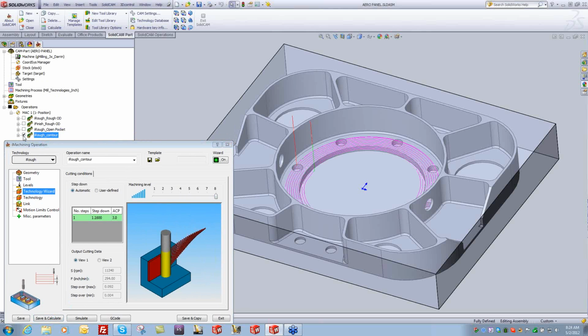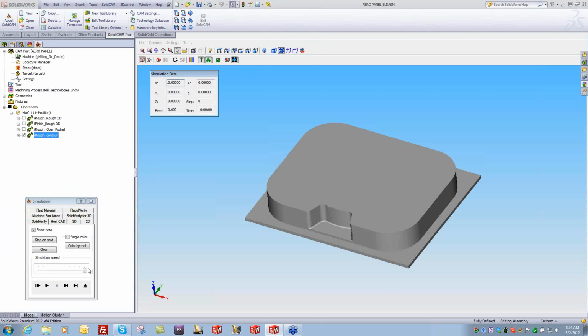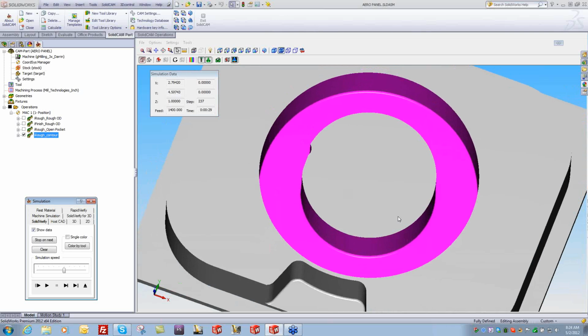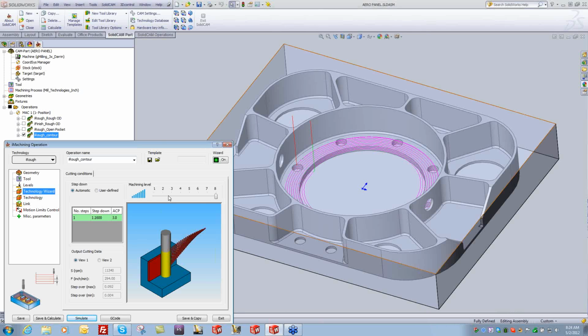And if I did that right, we should get a good tool path, which we did. And we'll turn that down a little bit and let it run. Now, this is assuming that the material in the center has been cut out. That's why it's going to start where it starts. We're assuming that this material is already gone. There's no reason to cut all that out again. Now, of course, if you had to cut that material out, you just simply don't define an open edge right here.